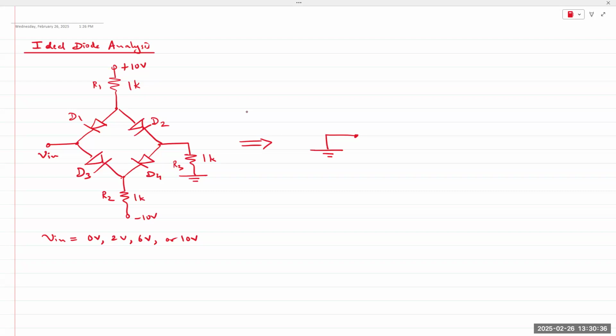Right? You have your mobile devices with you. They are not physically connected to ground. But if I was to draw a circuit for that cell phone or the tablet or your laptop, I would mark that negative point of the power supply as ground. That simply means it is the common reference point. So this is the common reference point. This is 0 volts. Make sense?